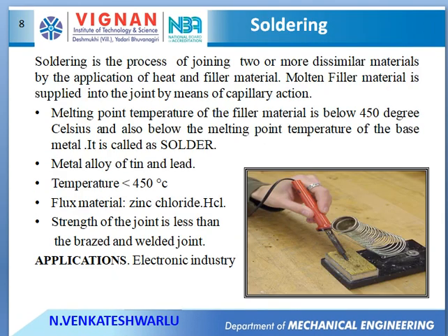Next topic is soldering. Soldering, brazing and welding are permanent joining processes. In soldering, brazing and welding, heat is required and filler metal is also required. But welding is suitable for similar materials only, and the amount of heat required is more compared to soldering and brazing.